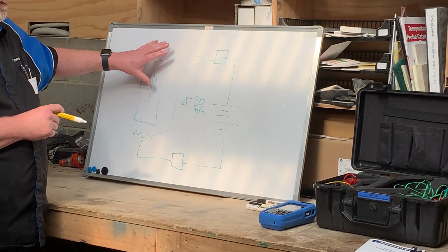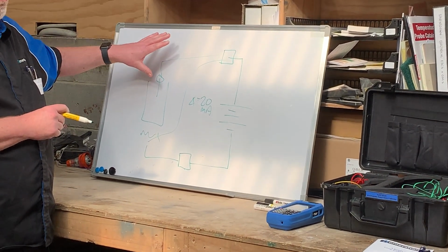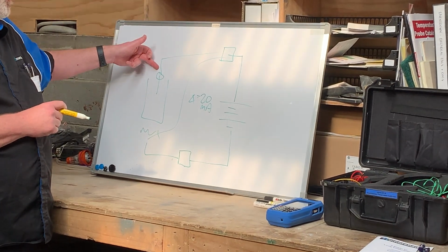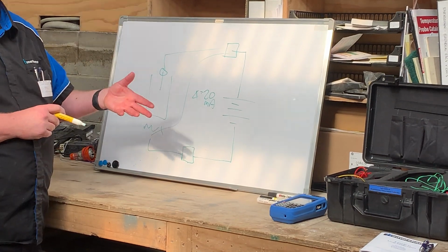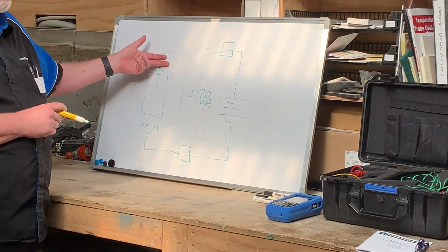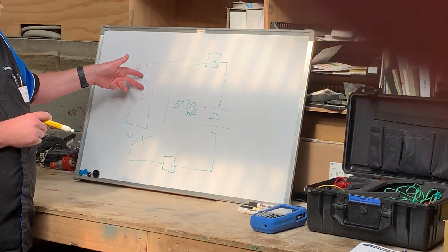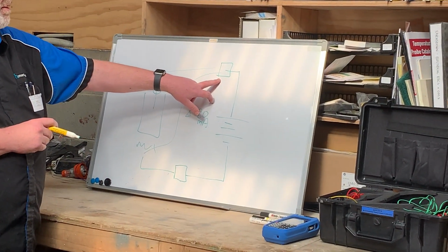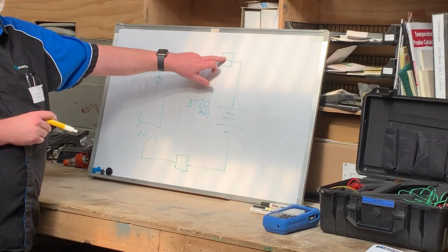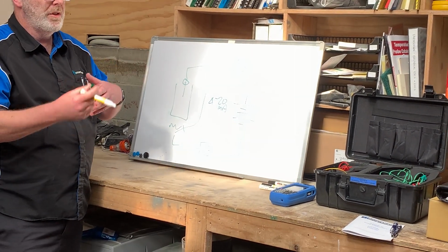In this sort of setup, many things can go wrong. Most typically, the sensor that's in contact with the fluid gets corroded or worn out. So maybe, let's say it's a thermocouple. Maybe the thermocouple's failed. Maybe the controller is not responding in a linear fashion to the thermocouple that's in there. It's not converting the millivolts to the temperature.